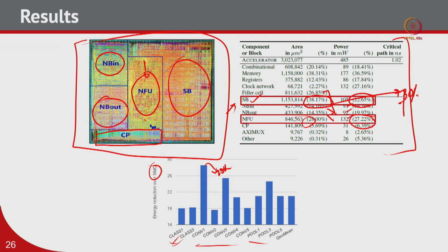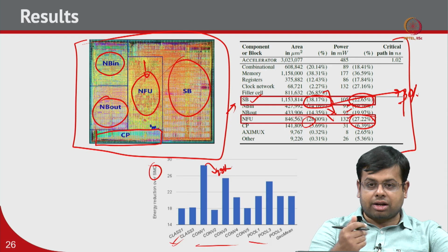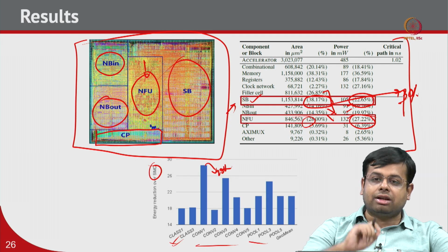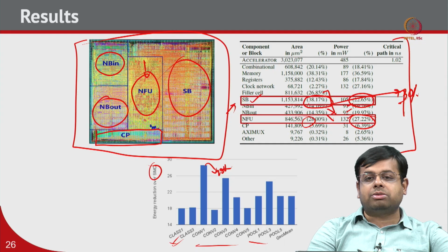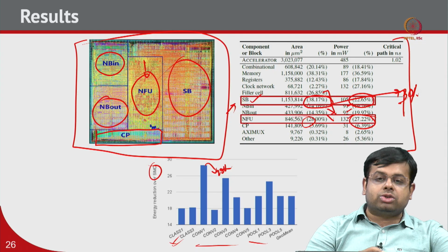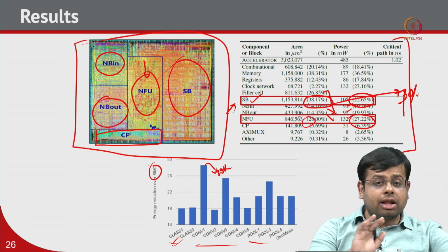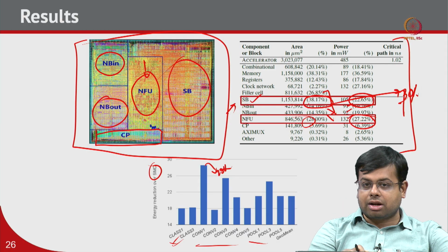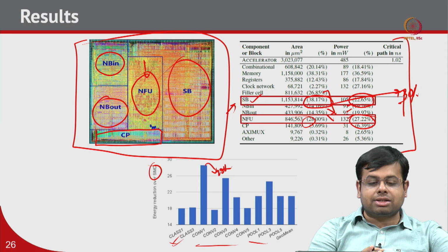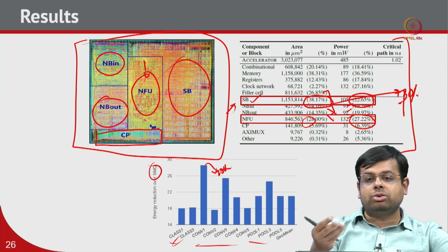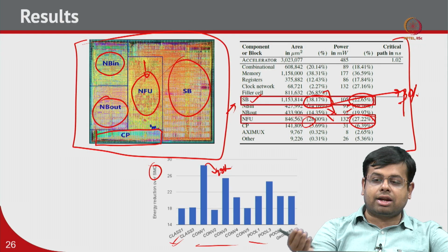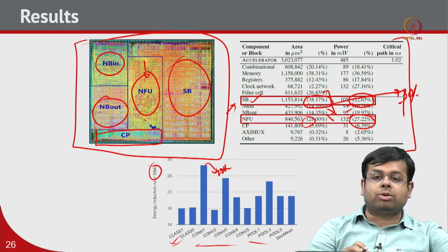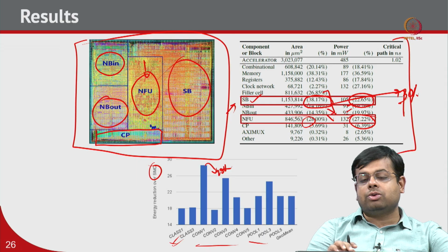So, that is one of the biggest advantages of this DianNao architecture, that they have the split buffers, right. As I already told, if we have split buffers, then there is less contention, correct. If we have less contention, then there is less latency in terms of memory access and all those things. Okay. So, overall we have seen this DianNao accelerator, which is very specific to convolutional neural networks. It has optimizations tailored for convolutional neural networks to reduce the latency, to reduce area, etc., and at the end it is providing very high benefit with respect to SIMD processor.